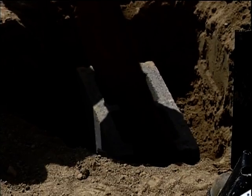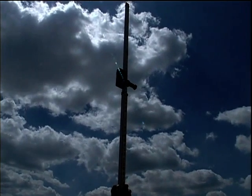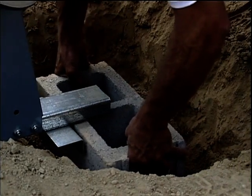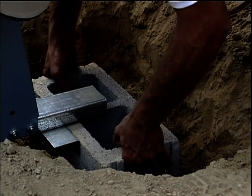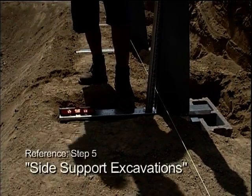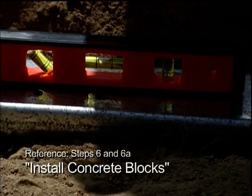Place a concrete block in the hole and check to be sure the top of the block is 3.5 inches below the leveled pool floor. Then, make sure the side surface of the block is 11 3/4 inches from the string line. Also check to be sure the block is level. Please refer to Side Support Excavations and Install Concrete Blocks in the assembly guide.